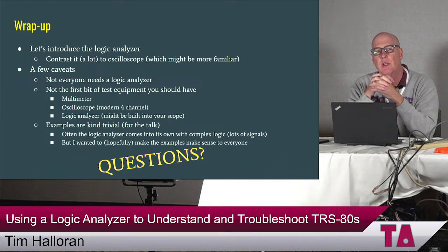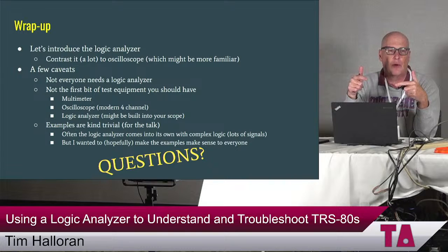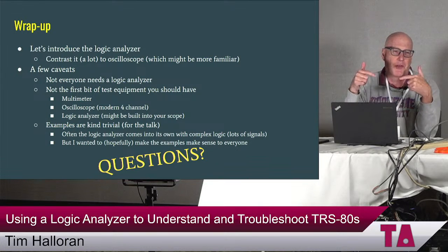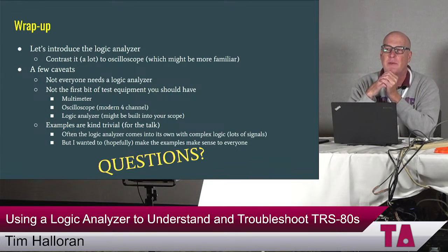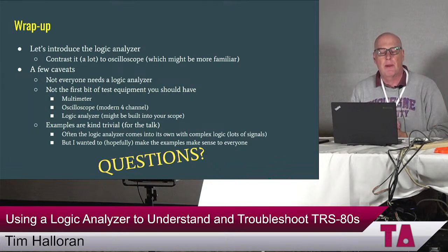But again, these are a little bit dicey because they tend to put these in the write-up about the analyzer, where if you use one digital signal, you get 2 gigahertz, and then when you add a second one, it drops down to 1 gigahertz and drops down further, so you really have to be careful and read what the sampling rate is if you use all of the channels.